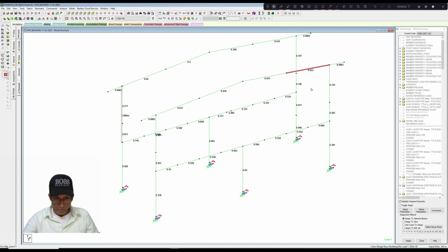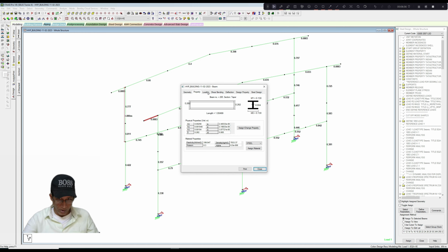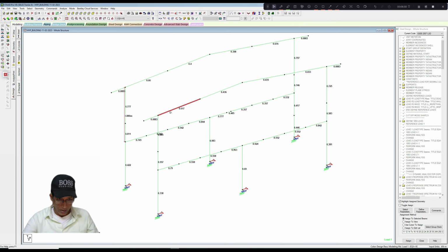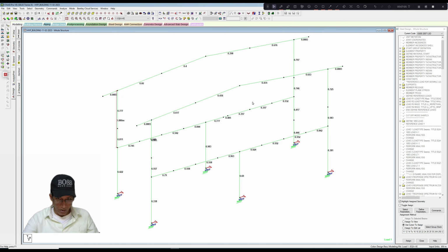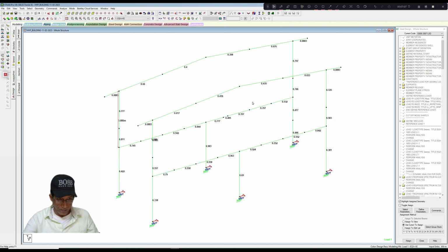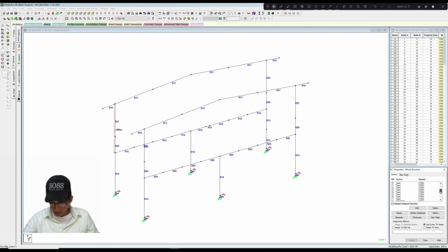Our rafter is a uniform section now. So this is 262, this is okay, 416. So the rafter still has a possibility of optimization. Let us first see what could be the possible optimization, then we will make it a taper section.